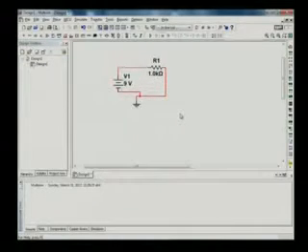Okay. So by theory, by the theoretical Ohm's law, we have this voltage source, then you have a resistance connected in a closed loop. The current will be given as I equal to V by R. So it will be 9 by 1 kilo ohm, that will be equal to 9 milliamperes. So that is theoretical.